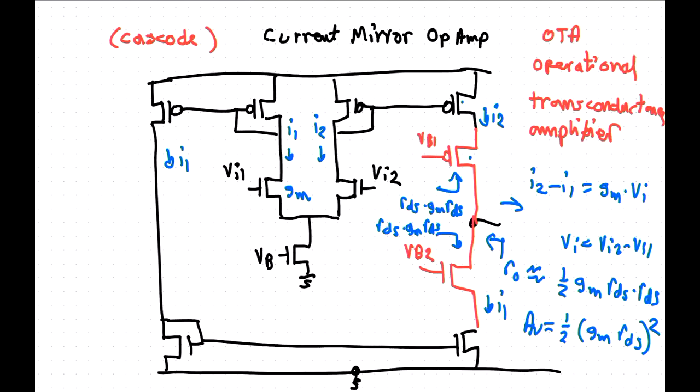Now, you can also just put in two cascodes. These two cascodes are what matter for the purpose of the gain. If you want to do it nicely, you probably put in cascodes on here as well, and then you put cascodes underneath here. So you have what's really a high swing current mirror here and a high swing current mirror here. You already had the bias voltage, and transistors don't cost anything, so you just get a better mirroring effect. And once you add it, you probably make the bottom into a high swing cascode mirror as well. But it doesn't change the operating principle at all.